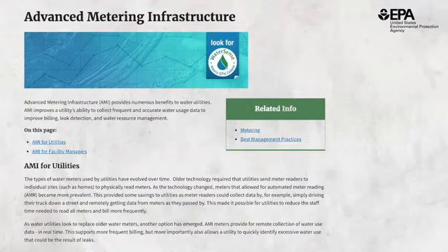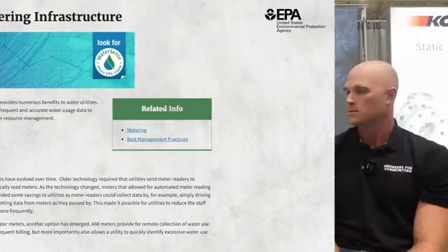We're looking for inflow. With the dry weather, once we have this data, the other thing that we use, and we're really kind of specialists in the area, is what's called an AMI network, Advanced Meter Infrastructure. This could be ITRON. A lot of cities, what you'll find in Colorado, they have AMI networks. There's a variety of them. You have ITRON, you have Sensus, you have Aclara, or they might have LoRaWAN, and a lot of them now are on cellular, where the water meters are communicating through these AMI networks. So we want that AMI data.